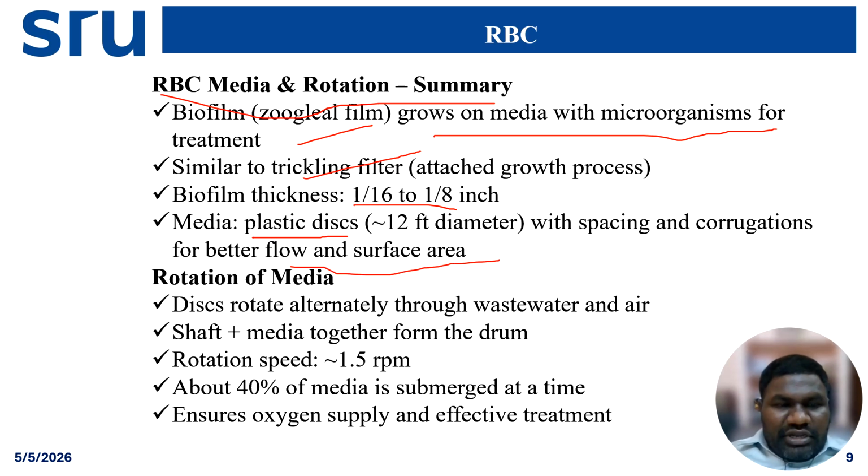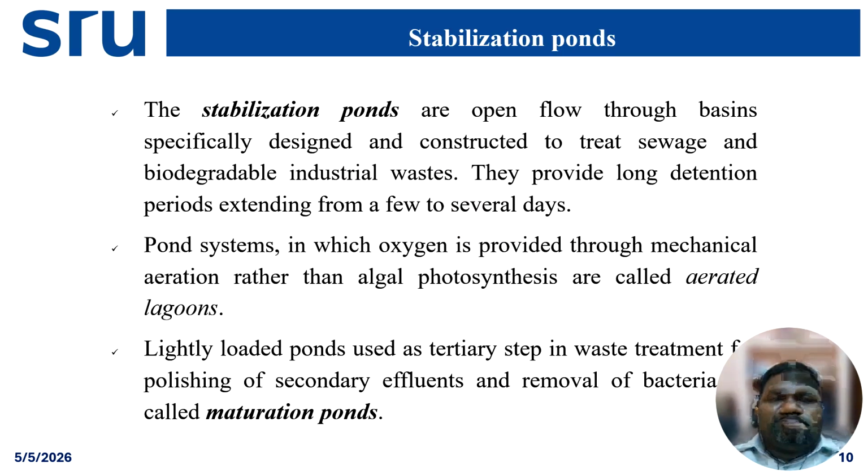So for rotation of media, discs rotate alternately through the wastewater and air. Shaft plus media together form the drum. The rotation speed we are maintaining is 1.5 rpm. About 40% of the media is submerged at a time, which ensures oxygen supply and effective treatment.